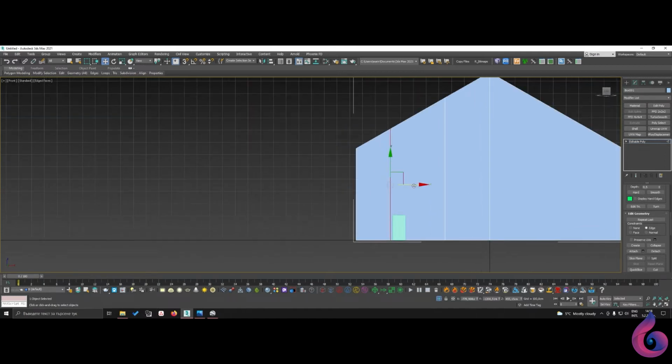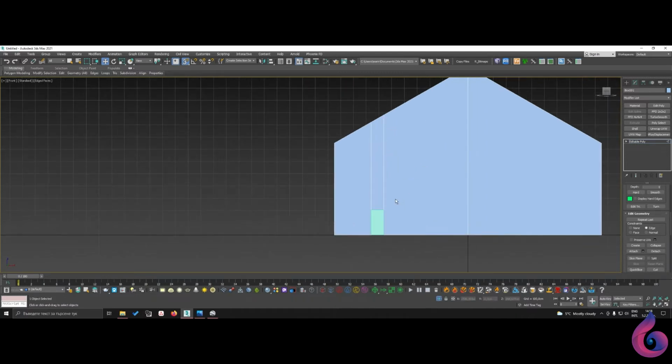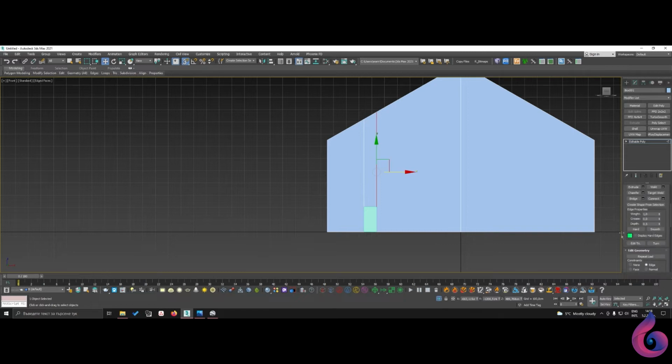It should snap the individual elements to the edge of the door. This is done from the toolbar and the Snaps toggle option. The shortcut to this function is the S button. Since we need the upper limit of the door, we select this edge, ring again and create another edge for the upper limit.